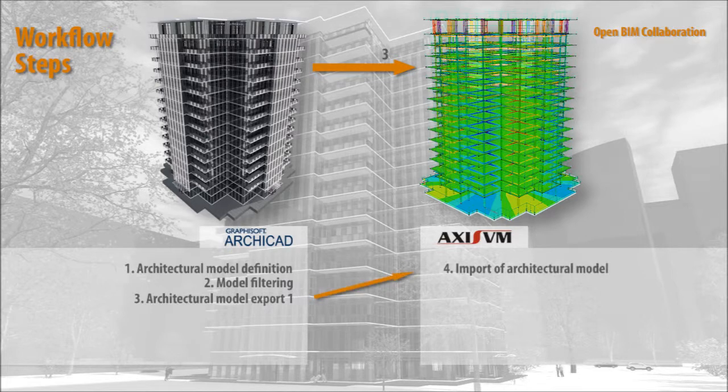Engineers receive the architectural model and open it. Engineers define the structural and the analysis model and its details based on the referenced architectural model. Engineers can query the initial profiles and materials defined by the architects. They add loads to the structure and run analysis and design calculations according to the required country standard and material